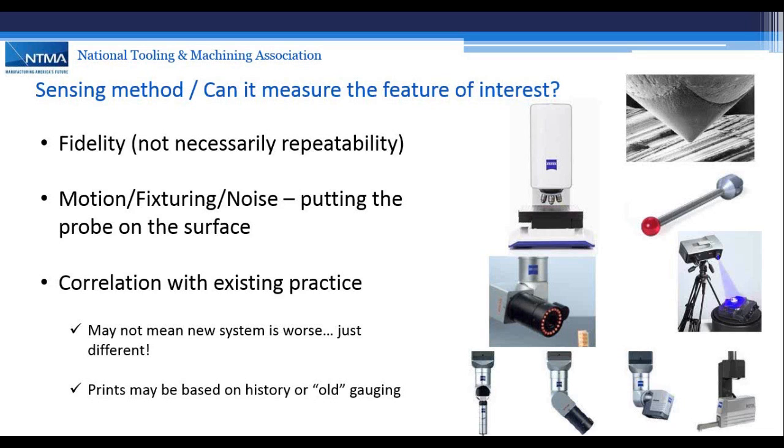Well, and those sensors are getting better resolution. Right. So what was once viewed as a flatness number with a new sensor could be a much higher flatness number. Right. We're seeing more details. And if we compare that to old tolerances, we could be scaring ourselves.